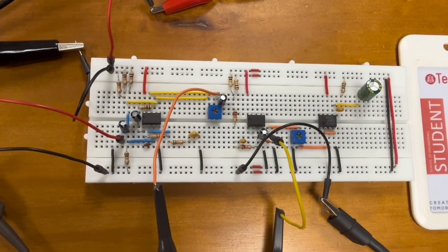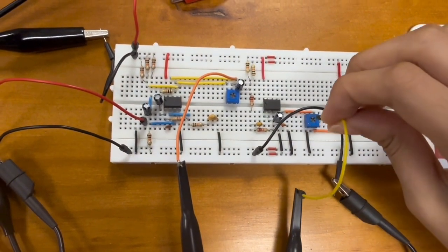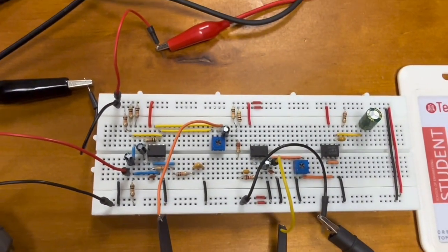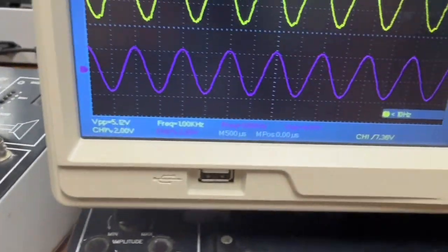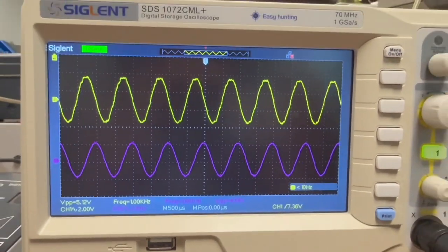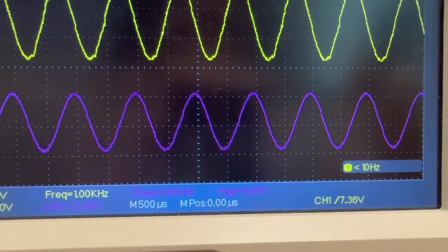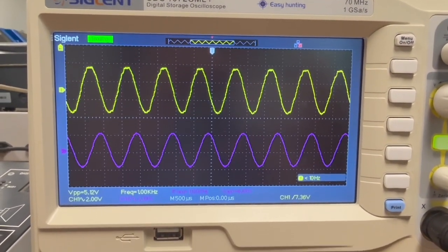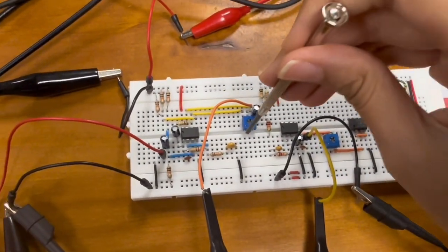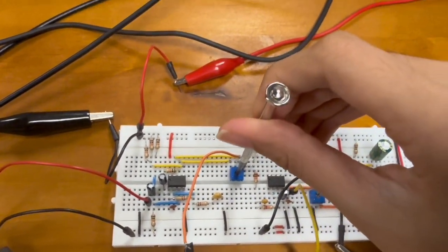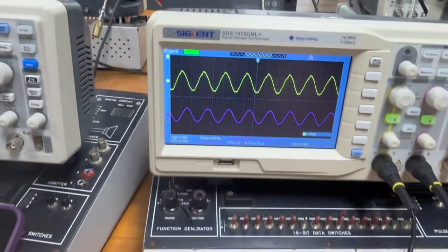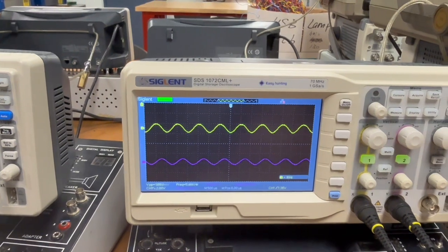By keeping TP3 at channel 1 and all patches untouched, we can place the channel 2 probe of the oscilloscope to TP4, and there we get a filter output voltage of 4 volt. The output waveform at TP4 will be determined by the output at TP3. Hence, by adjusting the trimmer at stage 2, we can control the output at TP4.